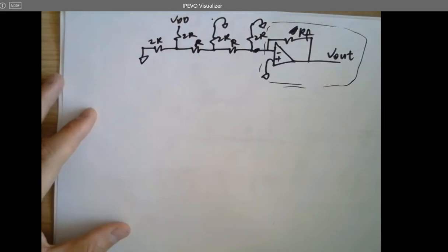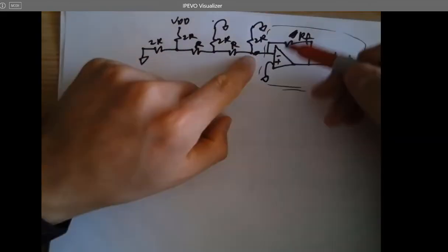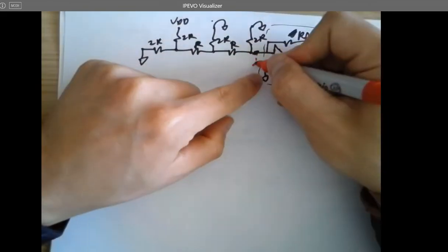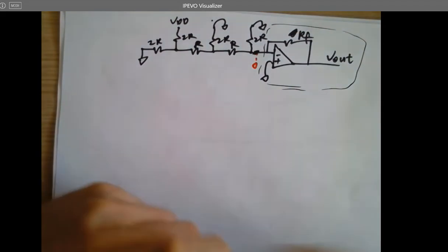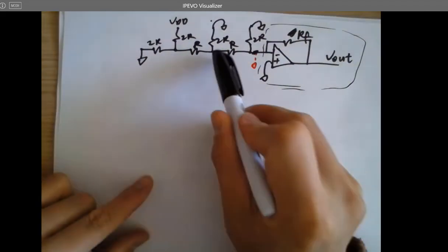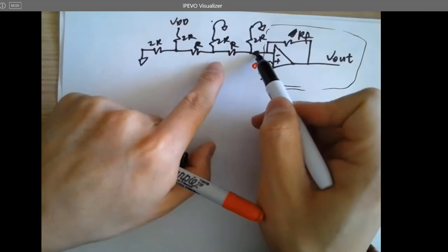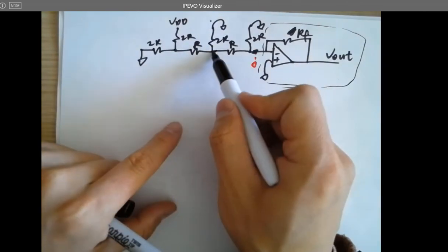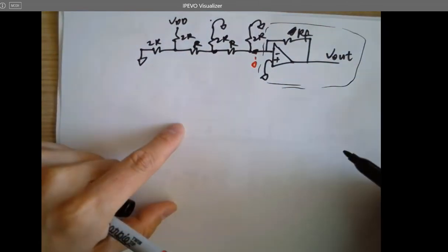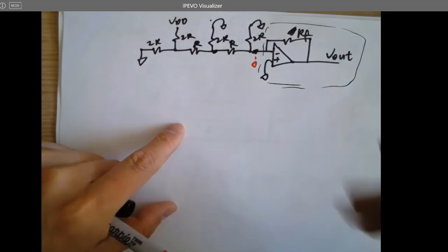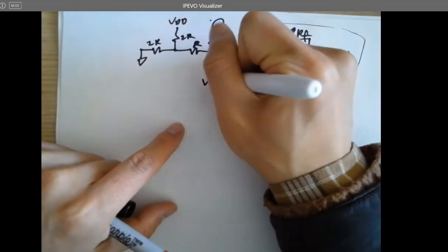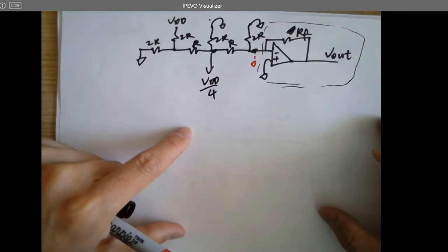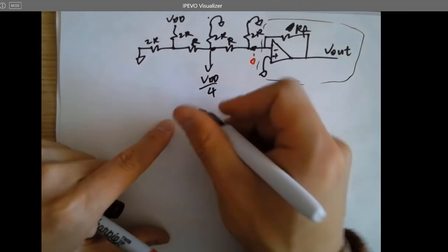So here's a trap, okay? What's the voltage here? That's an op-amp. An op-amp has a virtual ground, so it's actually 0. So you want to stop here. It's not being affected by this voltage. So what's the voltage here? Yes. Then you convert everything like this.